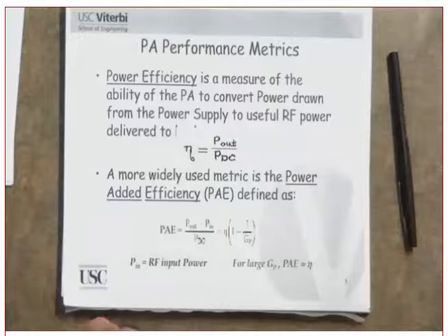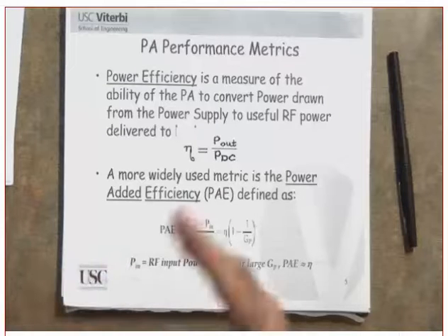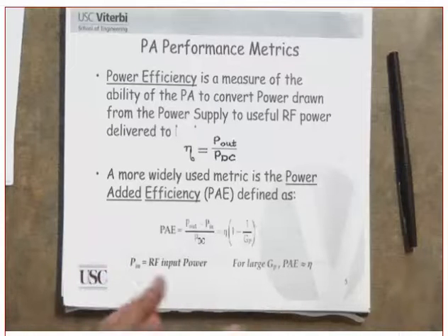The question is that if I'm using a non-constant envelope modulation technique, but I'm working in the linear region of the power amplifier, then you are not going to create those regrowths. It will not regrow. Why? Because a linear system, which is what is approximated if you are operating in the linear region of your power amplifier, does not generate new frequency components that were not present in the input. Always remember that. If the input does not have that frequency component, it will not show up at the output. Clear?